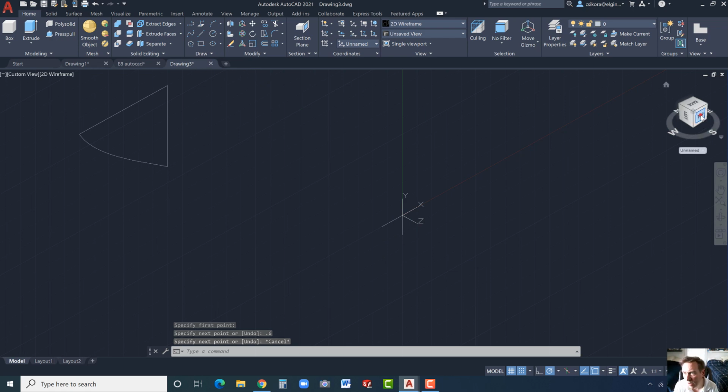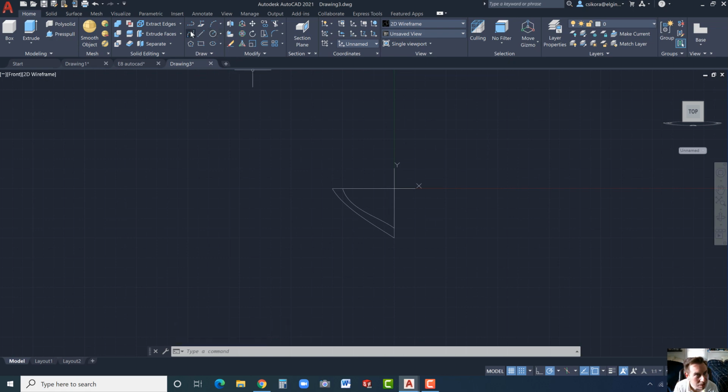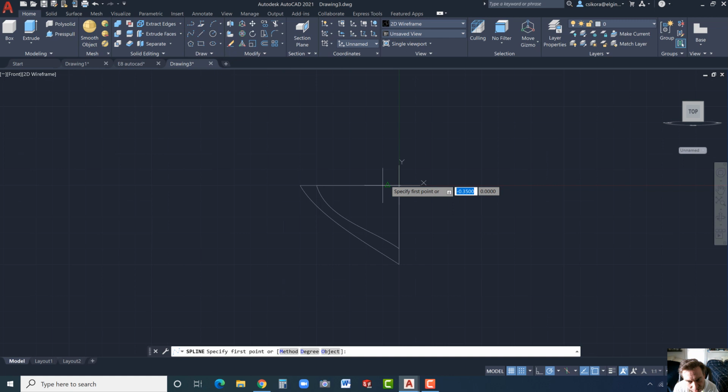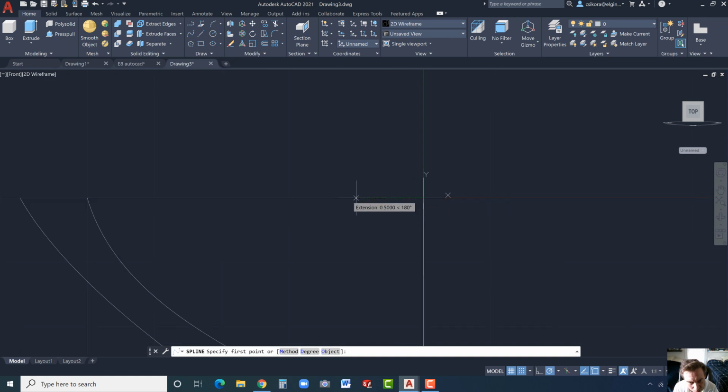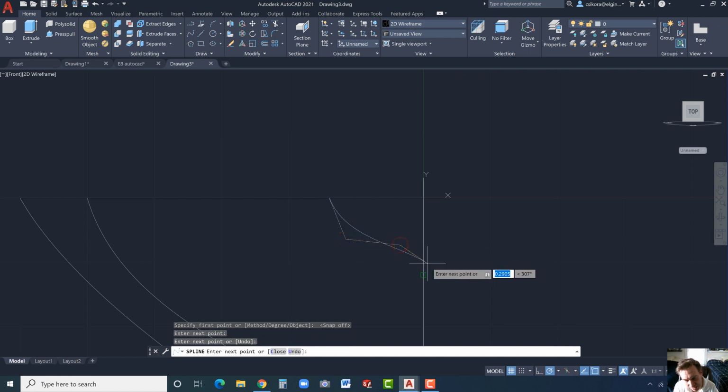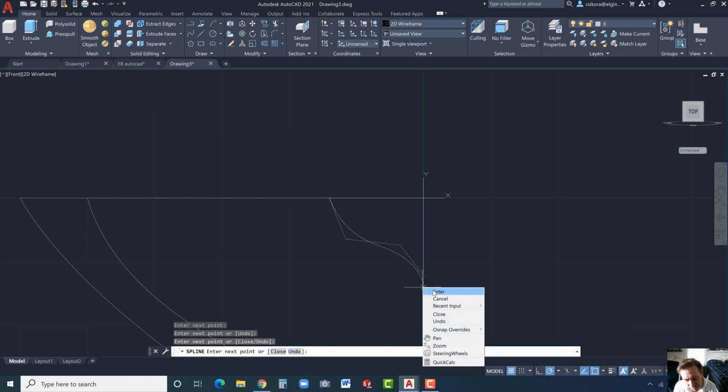And we'll go ahead and go to top again and rotate it clockwise. And now it's kind of hard to see, but you're going to be able to use the spline tool and snap to those points there. So I believe that's one of them right there. And actually I'm going to turn off these snaps. All right, and let's find, there it is. Click on that point. You have to kind of scan through. Go down, click, drag, and now scan and find that point there. Click, and then down and right click, enter.